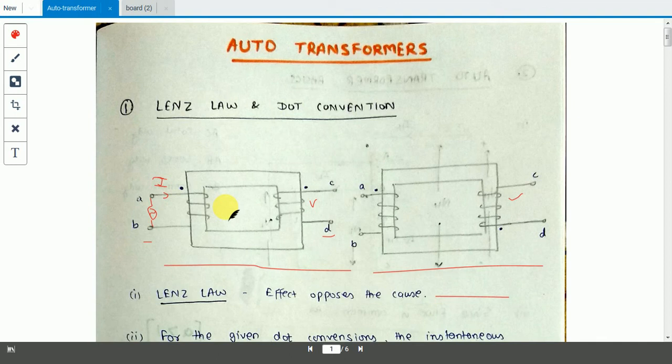You have to make a fist. Consider that a current-carrying wire or rod is in your hand. The curling of the fingers represents the direction of current in the winding, and the thumb represents the direction of the magnetic flux. So if the direction of current is from left to right, what will be the direction of magnetic flux? It will be from downward to upwards, like this, phi 1.